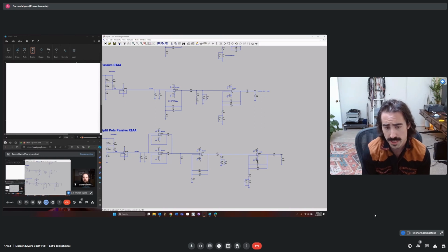And what do I mean by high bandwidth? Because when you think about regulators, you think about DC. So how's their bandwidth? The answer is it's an attenuation bandwidth, a rejection bandwidth: if we were to insert noise across a frequency band into the input of that regulator, how much does the regulator reject and attenuate on its output?